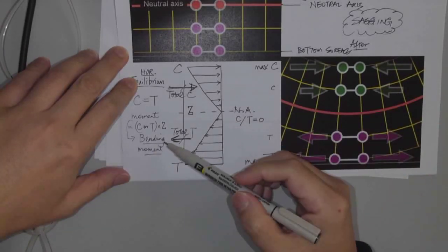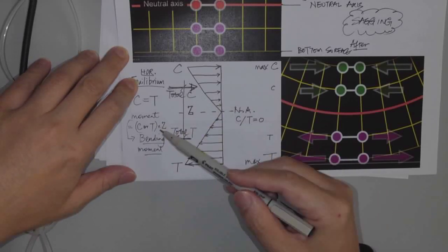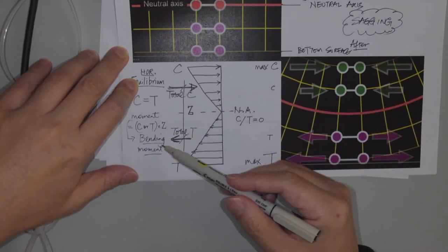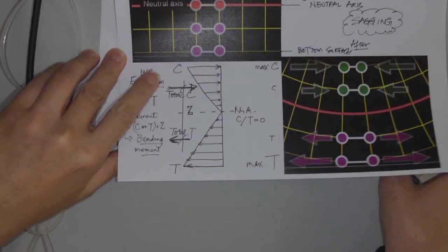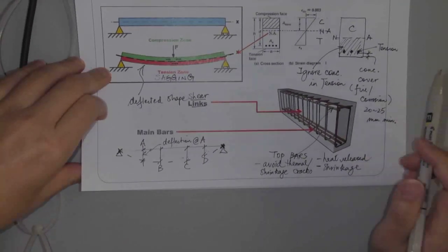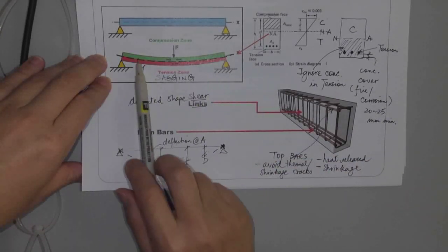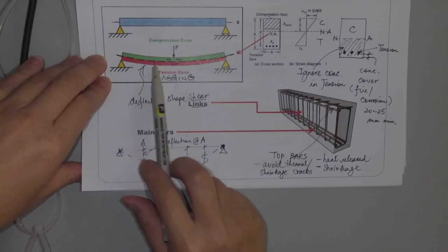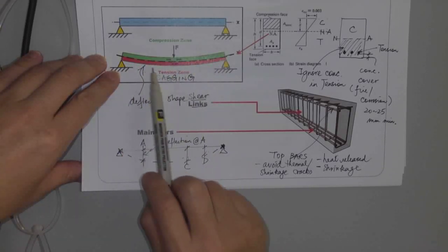And of course, you don't need to do any calculation for this formula. I just explain what bending moment is about. And then we covered a few examples. The most important thing in these examples is you need to know how to sketch the deflected shape based on the given location of the supports and the loading.